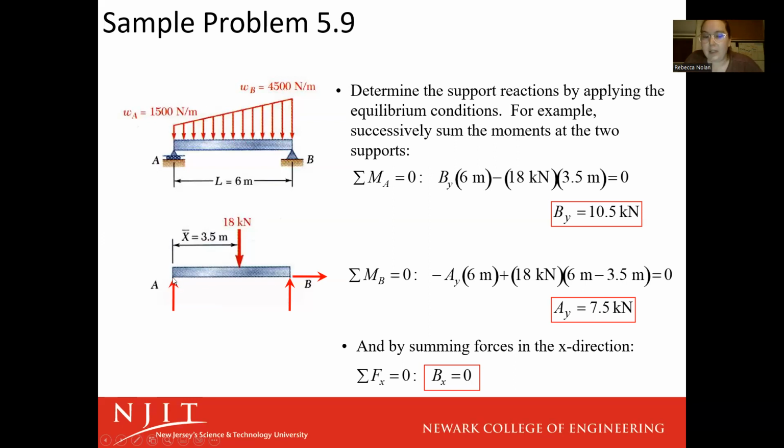A is going to be just as easy because remember, I'm forgetting the name of it, but we can move a force along its line of action without impacting the moment. So if we were to evaluate this, the line of action goes straight through that point. The perpendicular distance is still 0 for Bx, right? So if we were analyzing the moment about point A, we would have 0 moment impact from Ay, and we would have 0 moment impact from Bx.